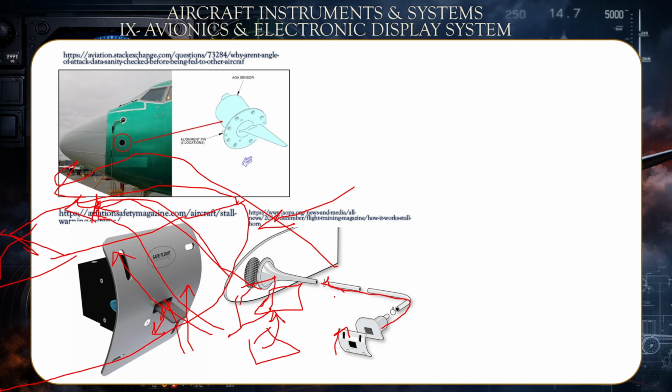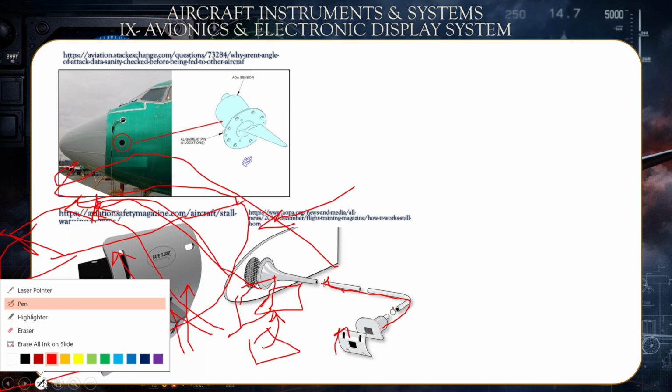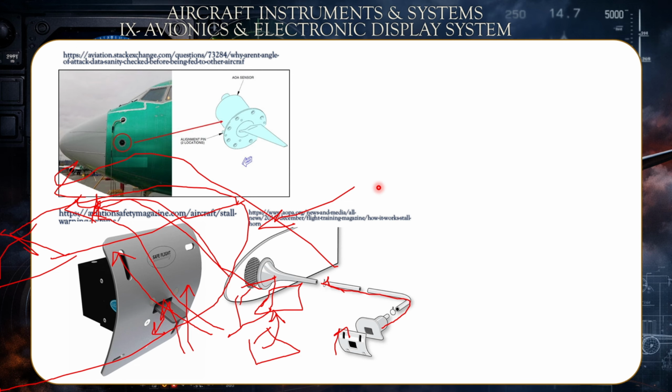Okay, so this is very important to warn the pilots preemptively so that they can take the proper action in order to avoid the aircraft's full stall, where the aircraft would fall from the air. In such a case, what the pilot should do is lower the nose and increase power. In fact, you increase the power first, then you lower the nose in order to gain more airspeed.